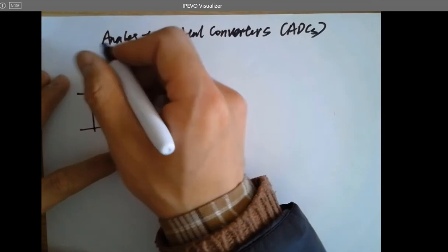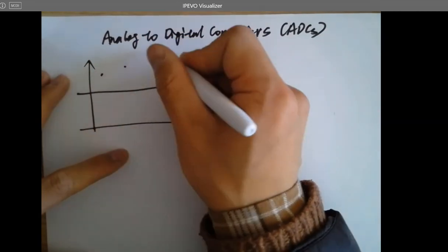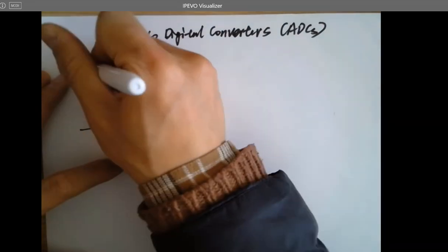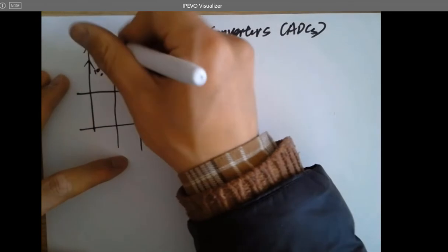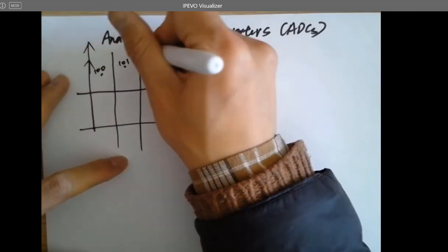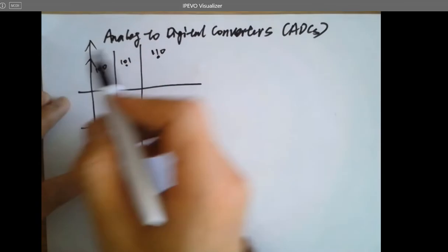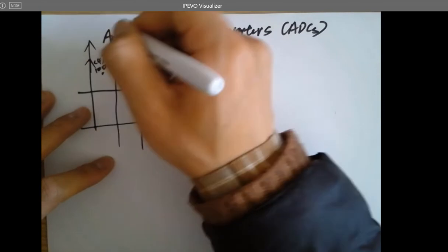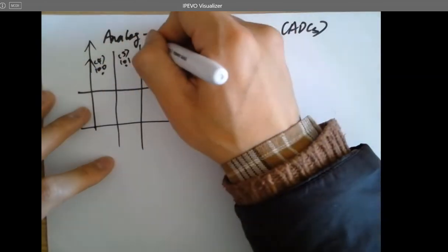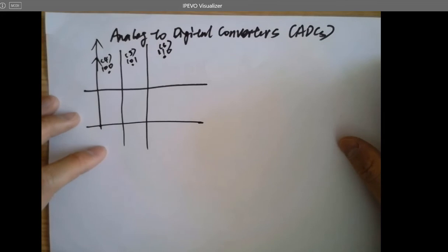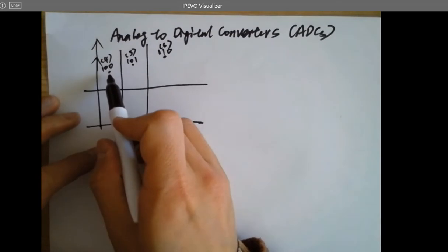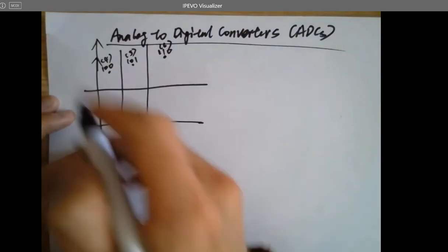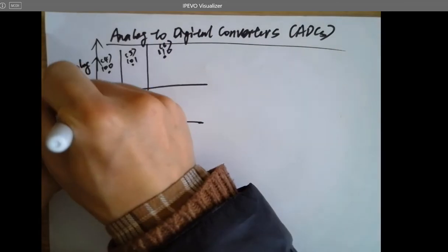For example, here's the analog signal, the first point, the second point, the third point, in these 3 cycles. So this is 1, 1, 0, 0, for example, 1, 0, 1, 1, 1, 0. Even though I label them as digital numbers, you should know that this is actually 4, right? 5, 6. So 3 analog numbers, and it's a 3-bit. So the ADC here is a 3-bit ADC. Here's the digital signal. That's analog, that's digital.